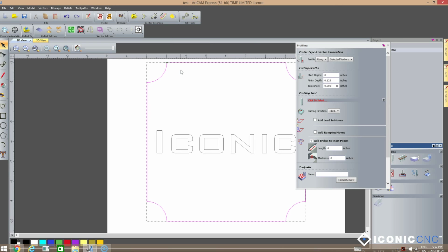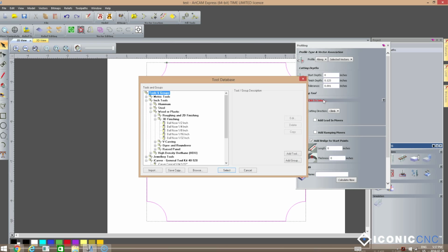If you set that number quite a bit higher, what you end up doing is getting sort of choppy corners, because the tool's path is trying to take its most economical way to get around that corner. And if we allow it to, say, take 1/10 inch bites out of this, then it will not create a nice smooth radius. So 1/1000th of an inch for most applications that we work on is going to be plenty high.